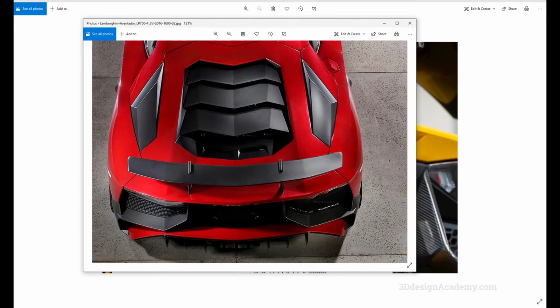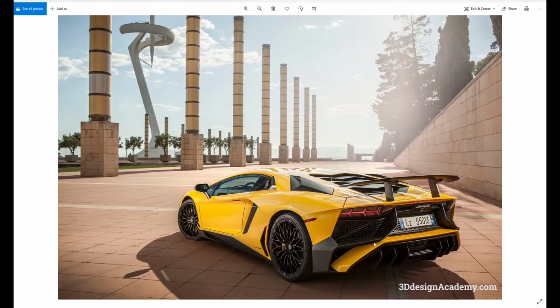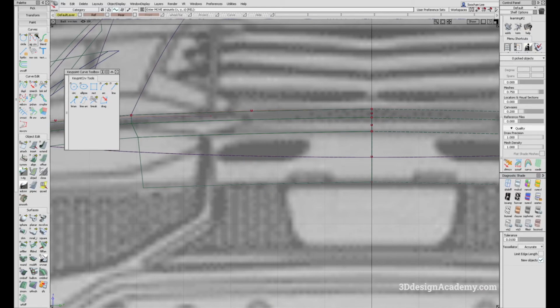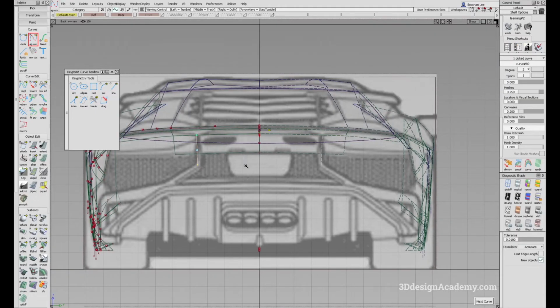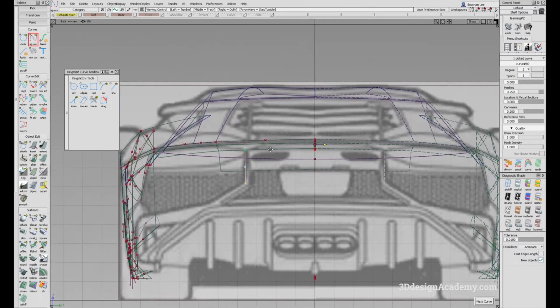Okay, so now let's go ahead and develop more surfaces over here. So looks like this one, I'm going to grab a degree 2 curve like this. This is definitely a little bit different from the orthographic drawing. As you can see over here, it's actually pointing outboard as it goes down, and it's almost parallel. I think it's in line with where the wing is supposed to be.